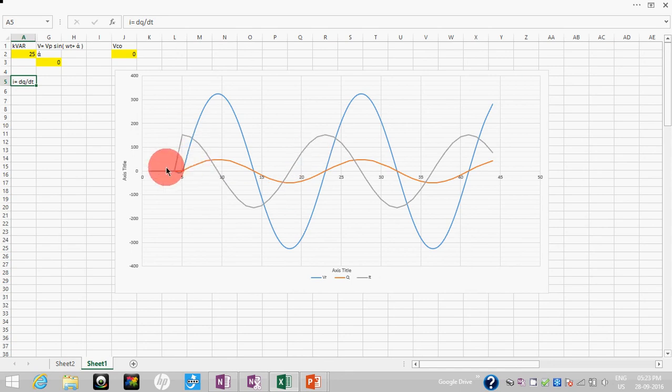So we will find this kind of graph without any high inrush current when we switch the capacitor bank at 0 voltage, when the capacitor initially has no voltage. So Vc is 0 and Vs is 0, so dVc by dt is 0. The rate of change of voltage across the capacitor is 0 at this point in time.